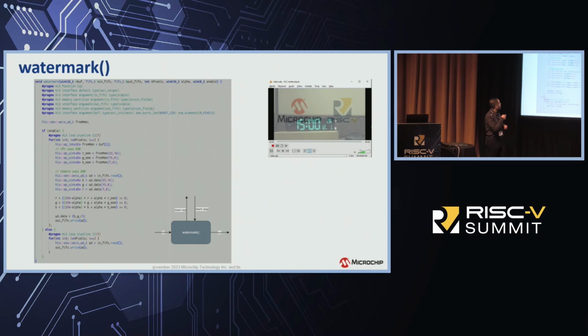All these pragmas that you see here in the function are basically just hints to the compiler to tell it how you want the hardware to be generated. And just to give you an example, this one, the AXI initiator, is telling the compiler, please include a mini DMA inside so that you can burst transfers into DDR memory with just one line.